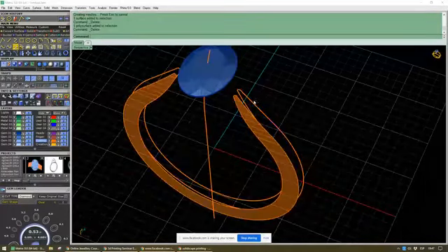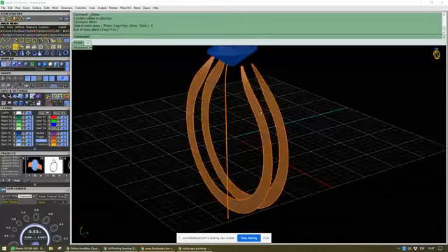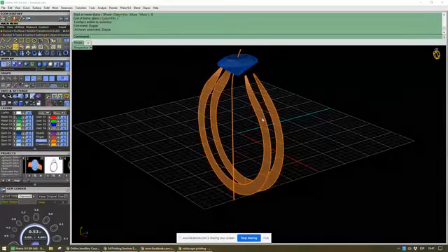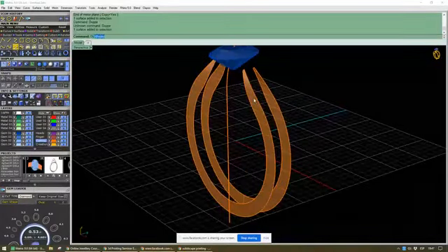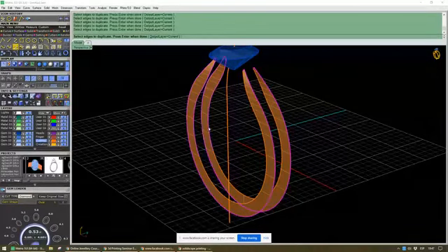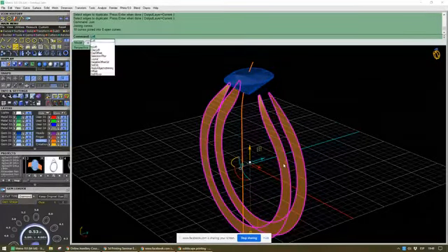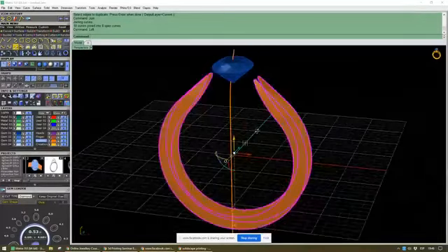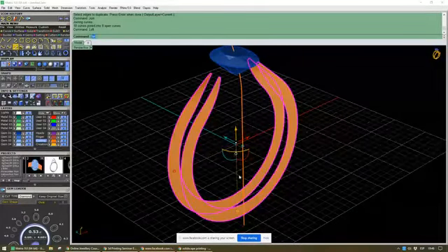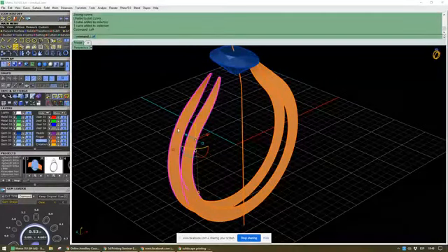Okay, so I have one side of the shank, and if I mirror it to the other side, I have the other side. Then I can just duplicate these edges and these edges, join them and make a loft. Whoa. Join them first and join. That's weird. Okay. I'm gonna loft this first.